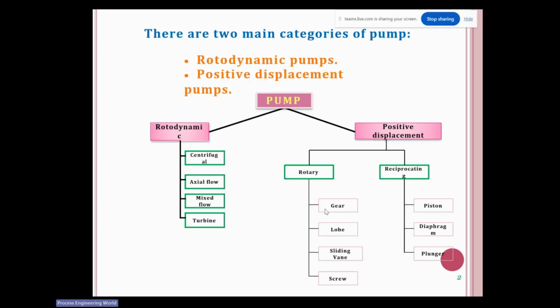The solid particles can hinder the operation, because the impeller of the centrifugal pump can get damaged by the force of suction. So in that case centrifugal pumps are not used; we use screw pumps. Screw pumps are used around 2 to 5% in the chemical industry, where you are transferring slurry in some cases, while usually 90% of the time you will be using centrifugal pumps.